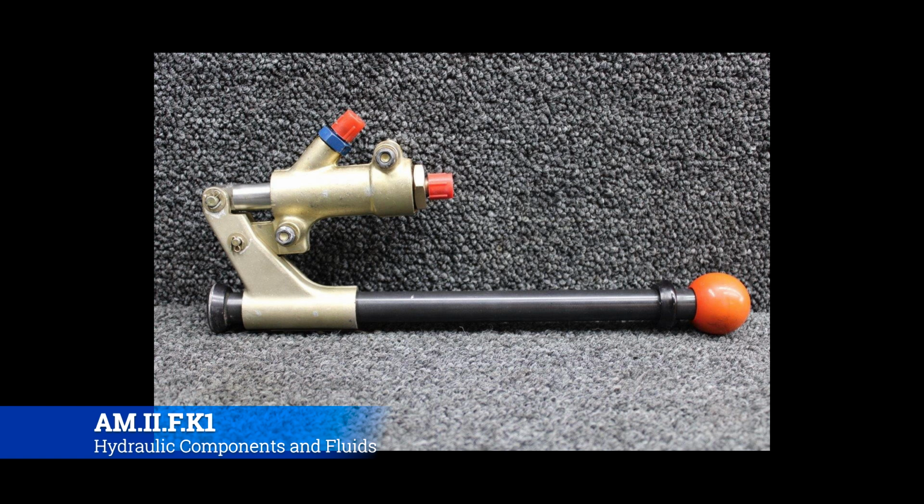You can actually use it much like you would raise a car with a bottle jack. This is a very similar kind of operation, where you'd be able to pump the landing gear down until they lock into place. You'll notice that the long black cylinder with the red ball on the end is a handle that's going to be in the cockpit. You're going to grab it. It's going to be mounted with those two mounting bolts that you see on the cylinder right there.